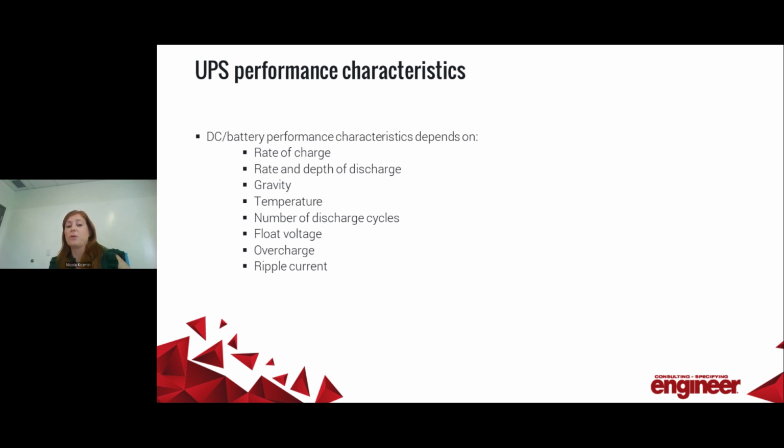The reliability and performance of the UPS is only as good as its battery types. There are 3 main types that I want to touch on that you will need to decide which to specify. Those are valve-regulated lead acid, flooded cell lead acid, and lithium-ion. Things to consider about each one of these are the upfront cost, long-term cost, physical size, containment requirements, code implications, and lifespan.